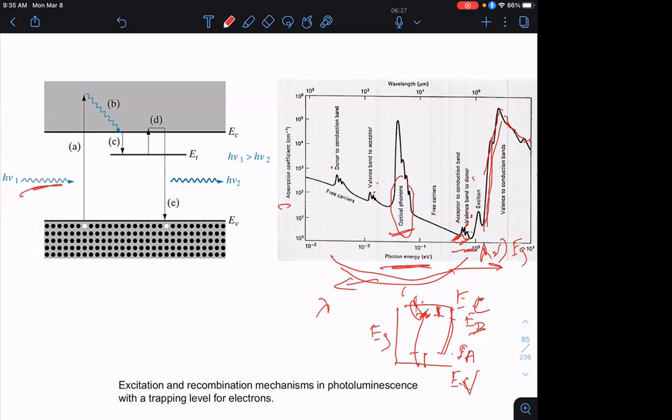So these absorption due to impurities are shown in more detail over here. So you can have direct absorption processes from valence to the conduction band, or as I said, you could involve the impurities. For example, these carriers in the conduction band, which might be initially at a very high energy. These are hot electrons, lose energy by emitting a whole bunch of phonons, then relax to this impurity level. Subsequently, it might be excited from the impurity to the conduction band and then fall down, or it could come from here to the valence band. So you have all these complicated processes that can go on. So from this photon energy, for example, you could measure what the trap impurity level is, okay?